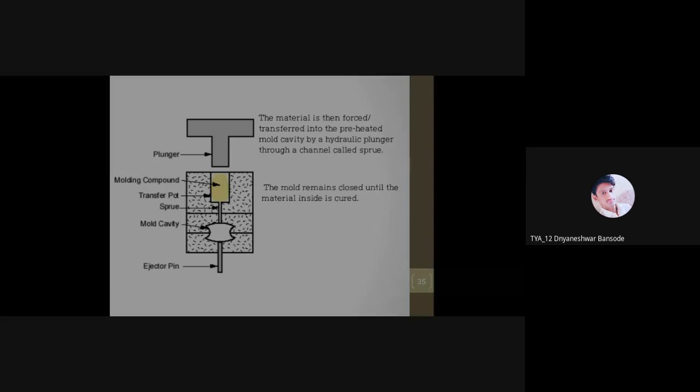First thing, plunger. There is a movement of the plunger, maximum movement of the plunger. So rather than going for manual movement, you can go for automatic movement of the plunger. You know the distance traveled by the plunger, so you can easily program that. So automation is possible in the movement of the plunger. Getting it? Through the plunger we are putting pressure over the material. This pressure range is not kept random. This is a fixed range.